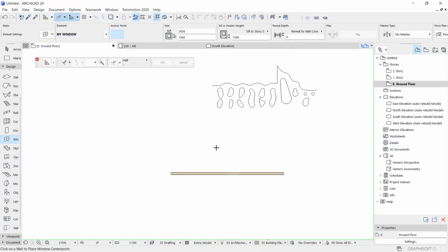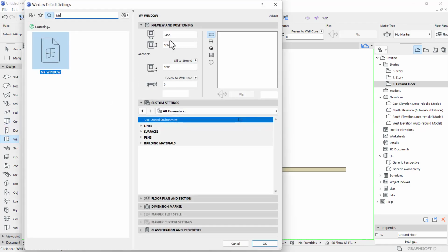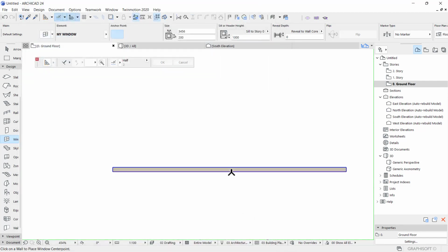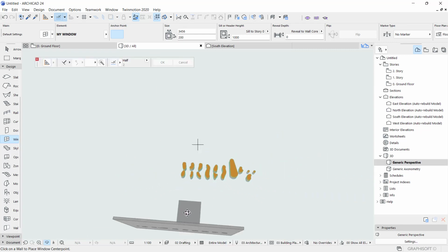So you come here and you place the window. Of course, you can check the location from the ground, like where is it from the ground. So now I will say let's have it like 200 mm from the ground, even 150. Let's do 200, because from the picture you are not going to have a very long wall. It's just going to be something sort of.